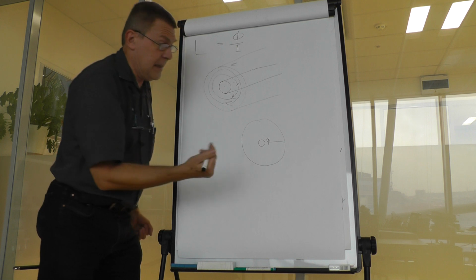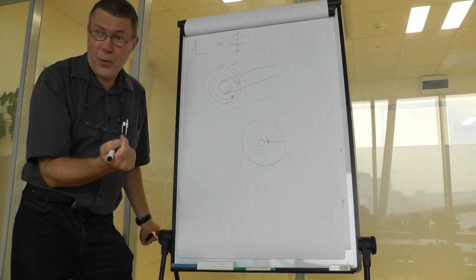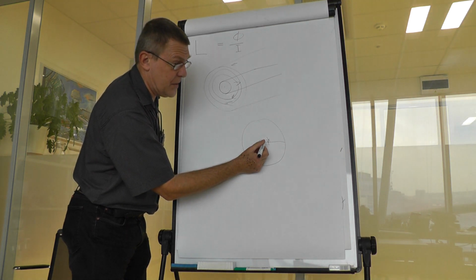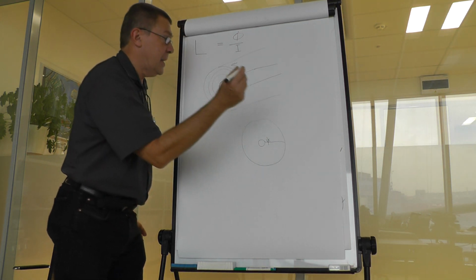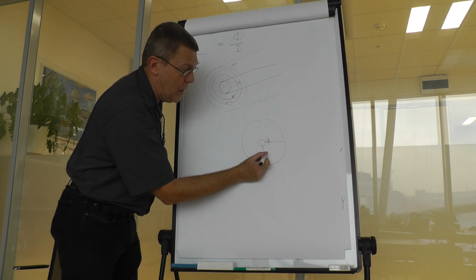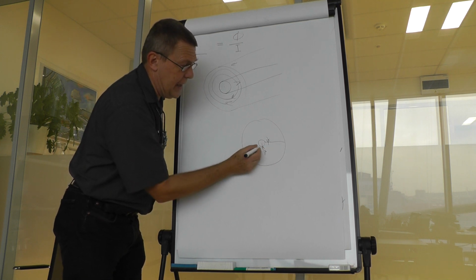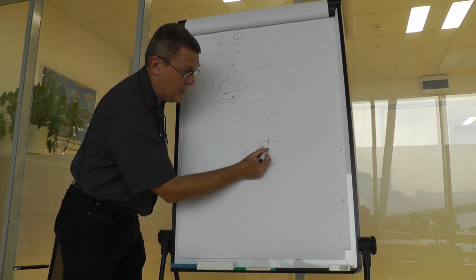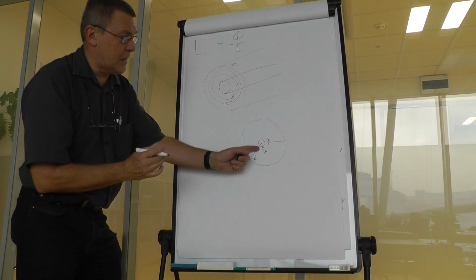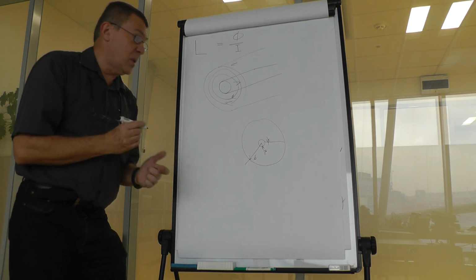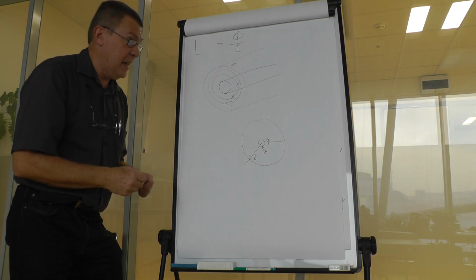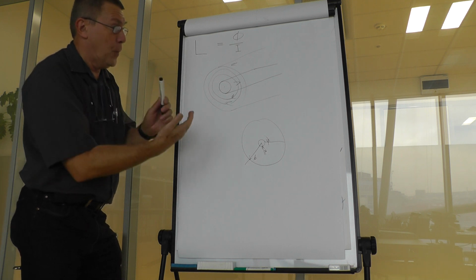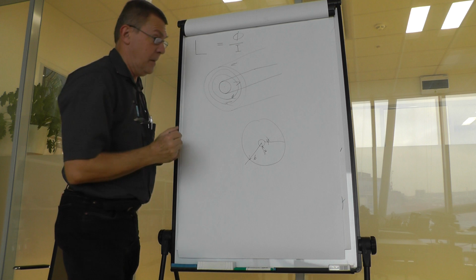Second, it is the shortest way for integration, and it directly runs from the inner conductor radius to the outer conductor radius. So to name it somehow, let the inner conductor radius be small a, and the outer conductor radius be b. So we have the inner conductor with the radius a, the outer conductor with the radius b, and now we would like to find out the magnetic flux that flows through 1 meter of that line.